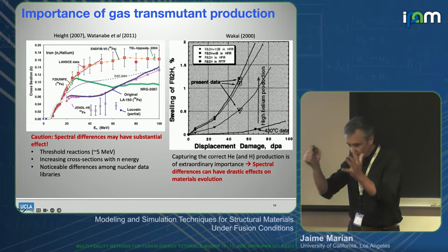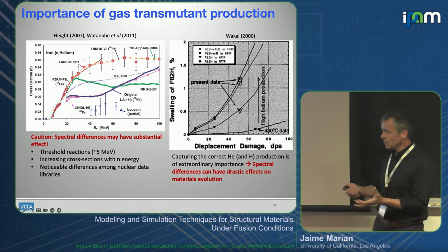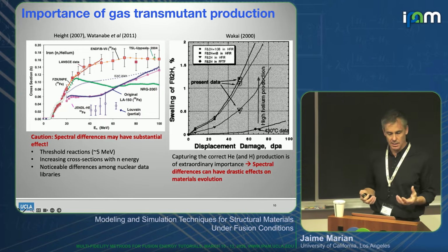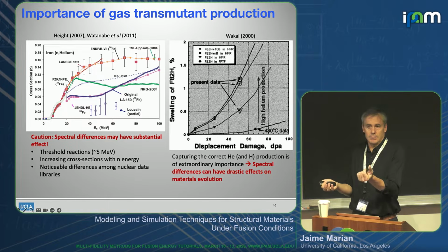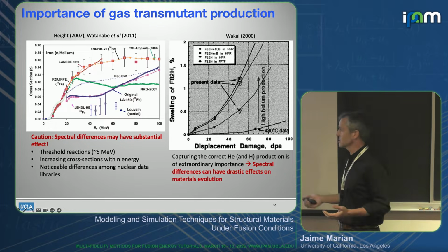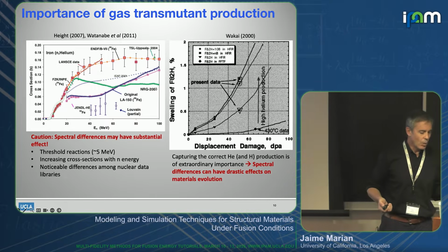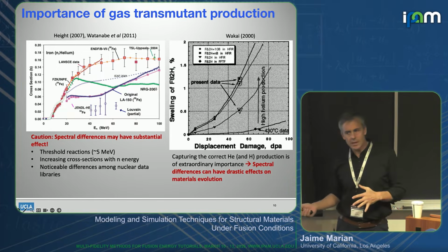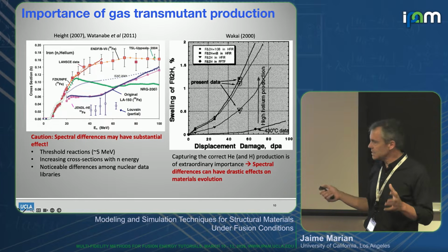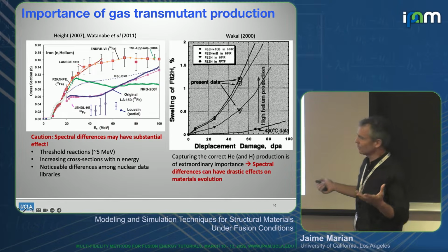Helium will coat every grain boundary. The grains will lose consistency and coherence, and the whole thing will just kind of become a grainy, useless mess in your hands. Okay, so helium and hydrogen are huge issues. Hydrogen, we can control it chemically a little bit because it's reactive, so we can throw things in there that will trap it and form hydrides that we can more or less control. Generally not, but we can try.